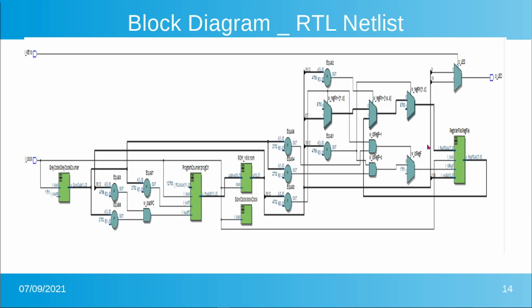You can see some of the stages of multiplexers into the register file and the control lines that control that. So sort of a good visual representation. It's not a horribly complicated device. For the parts that are their own VHDL file, if you double click on that part, you could go in and see what that individual part looks like, but this is a good representation of the block diagram.